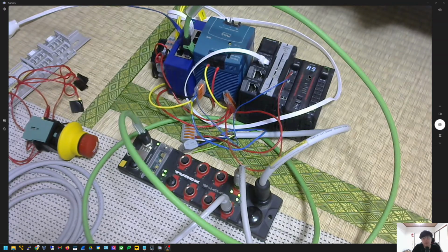Actually, no need to care about this number if it's normal. If there's any Ethernet or safety connection error, then it shows the IP address with the error by two numbers. For example, it'll show you 192.168.1.10 in hex format for each number. And now you see it's not flashing, so it means the connection is okay.